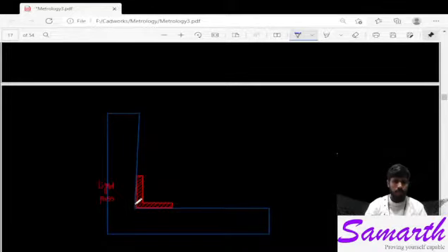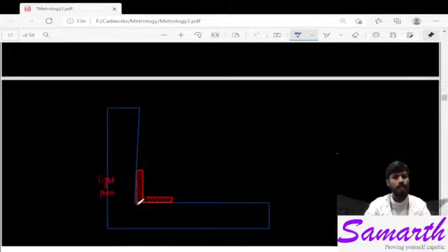If I pass a light from one side, and there is irregularity, that is, if the surfaces of the try-square and the machine component are not matching exactly, then the light which I am passing from one side will be visible from the other side. This is the way it is used, to check whether the surface is at a right angle or not.